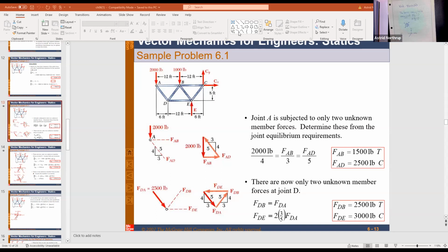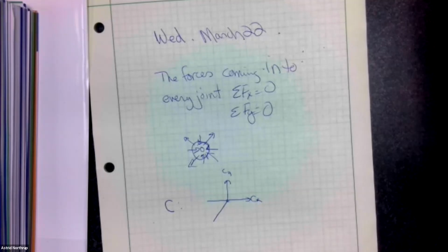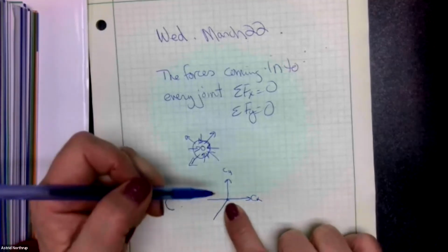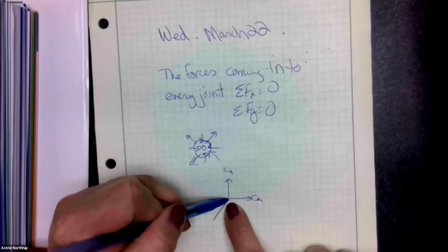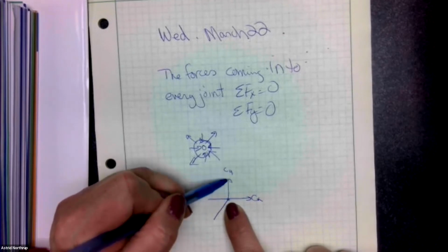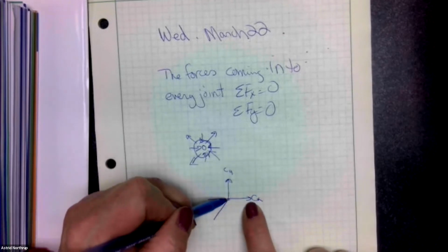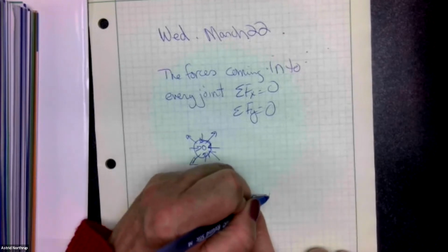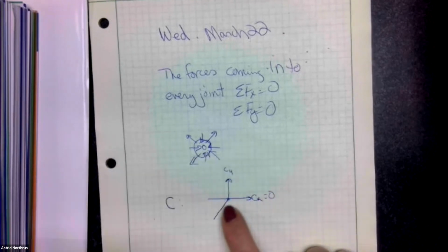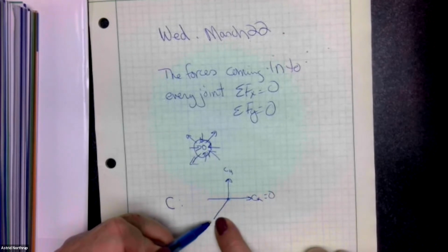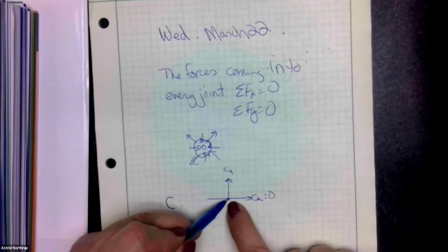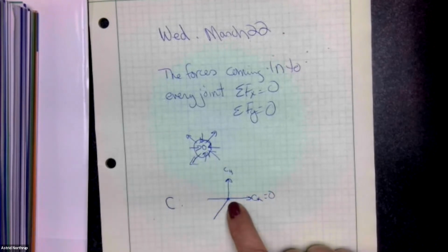So, all right. If you take a look at joint C in this particular problem, there's C sub Y acting vertically on it one way or the other, C sub X, which is equal to 0, we already determined that. Then there's a horizontal force here and a force here. In other words, the structural members that go into the joint can at that point be viewed as forces. So you're looking at what the force is being borne in that structural member going into the joint.